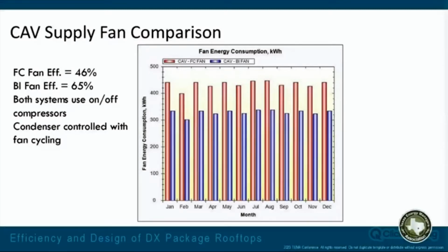And the way I came up with those efficiencies is I picked a CFM and a static pressure, and I selected 2 fans. And I selected fans as an engineer. I tried to select the best fan selection that had the efficiency, the turn down, had the ability to move up and down a little bit when the external static pressure wasn't exactly what was calculated on the drawings. It had everything in there.